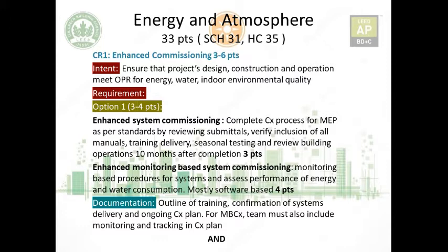Consider this situation compared to the previous one, where now we have a whole company or a consultant on board on site who is responsible only for commissioning. So in that case, the system of commissioning would be detailed. There would be submittals. There would be recording of all the documents. There will be proper documentation, filing, etc. There is training. So it is a complete commissioning process for MEP. The same standards would be followed, but the system now is more detailed and more professional.